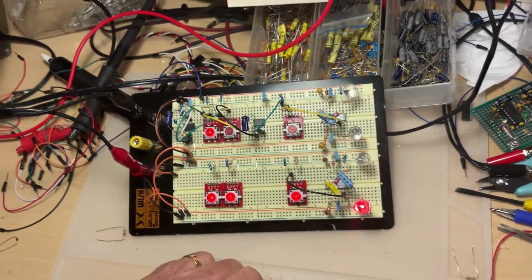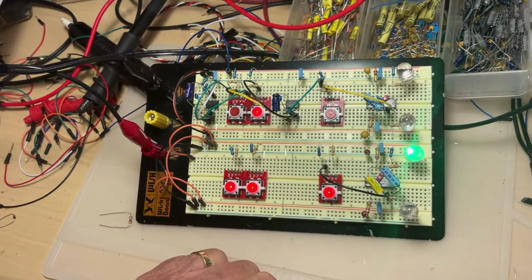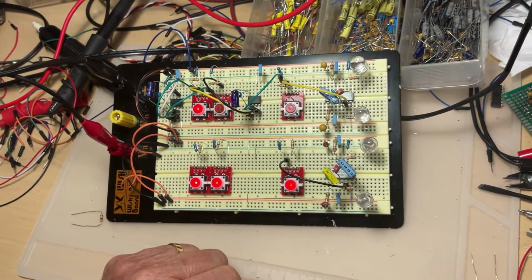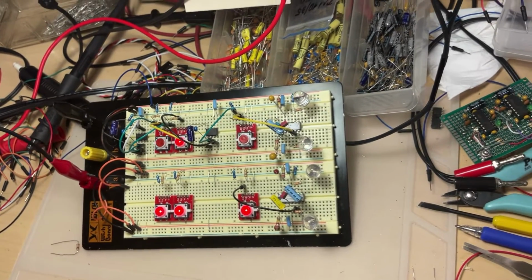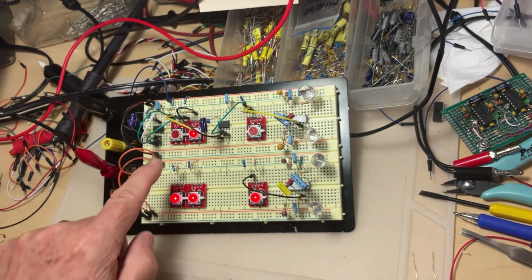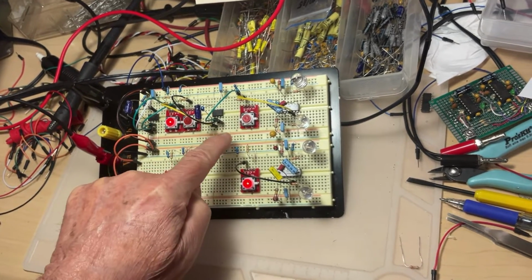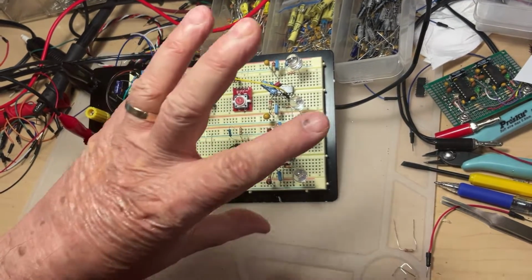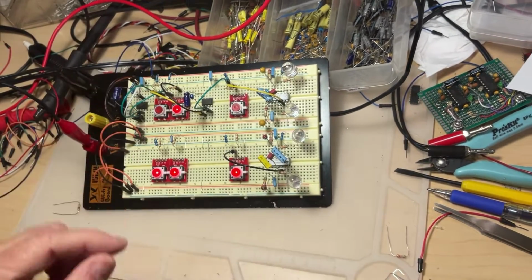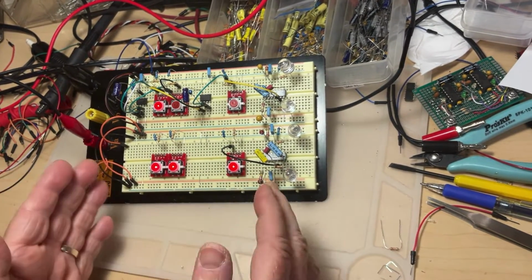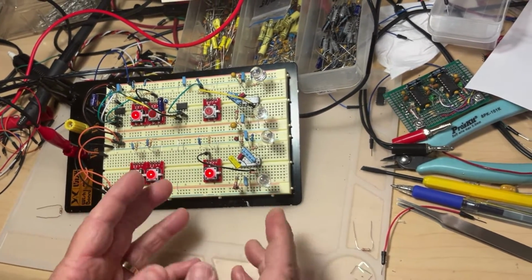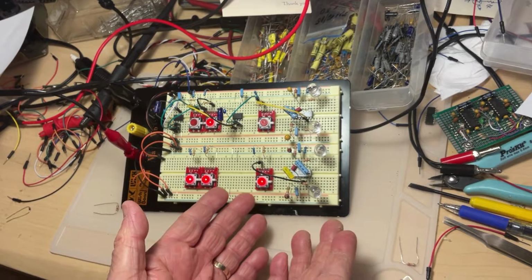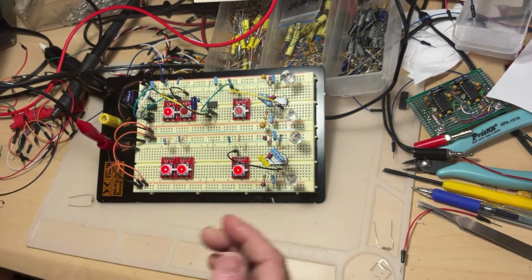Okay, so one more time. Very easy to calculate, the duration is 1.1 times the resistor times the capacitor. And what did we do so far? We made the distinction between the astable circuit, the bistable circuit, which was this one in the middle, and the monostables, even 2 of them connected together. We were also able to build any of them, because this one was a bit more complicated, I prefer to focus on this one, 2 monostables cascading together. And it was very easy to do, as you could see. You just respect the connections and you're done.